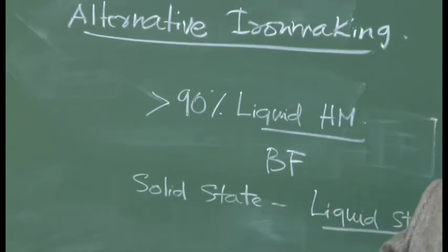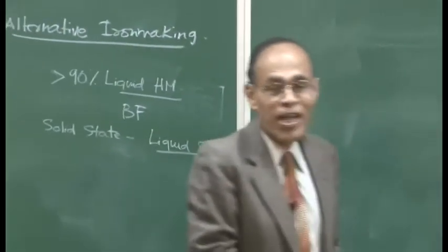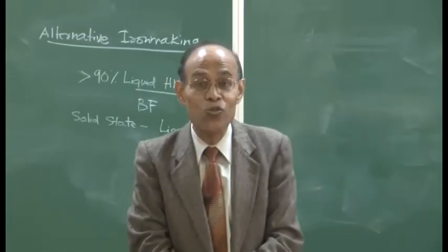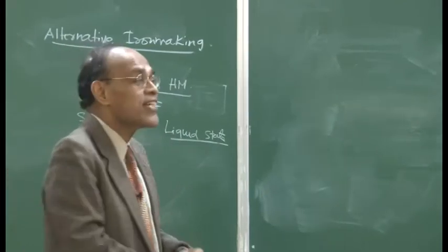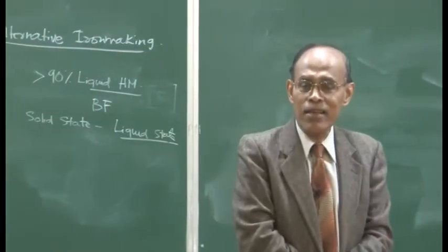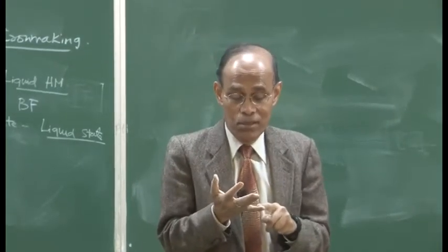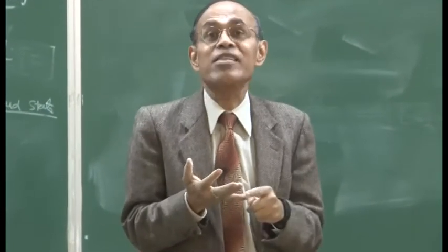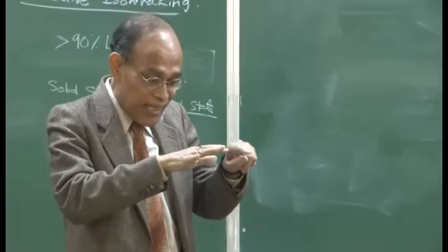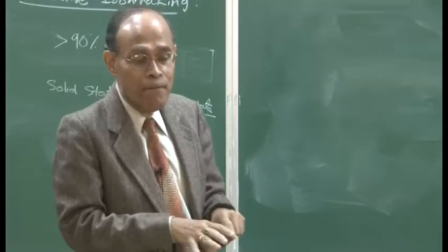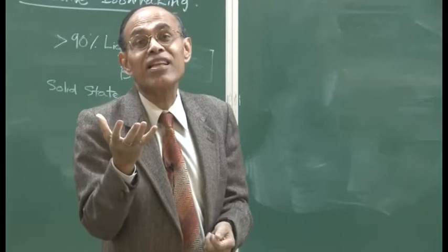dependent on metallurgical grade coal because it needs coke, and we know that metallurgical grade coals are very rare, they are depleting at a fast rate, they are very expensive too. Of all the reagents that you use in iron making and steel making, in terms of iron ore, limestone, coke, oxygen, etc., the most expensive on a per ton basis is coke, and the grade of coke is diminishing. Because in India, as I have indicated in one of the lectures, we get coke which contains 25% ash.